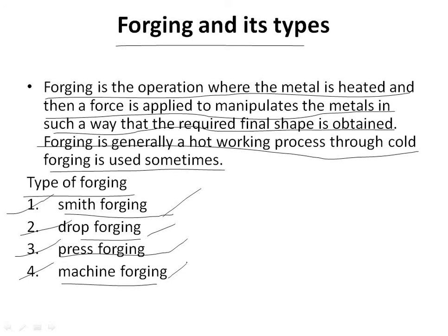Upsetting machines, called upsetters, are generally horizontal acting. The die set consists of a die and a corresponding punch or heading tool. The die consists of two parts, one called the stationary gripper die, which is fixed to the machine frame, and the other the movable gripper die, which moves along with the die slide of the upsetter. The stock is then held between these two gripper dies.